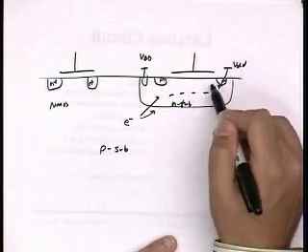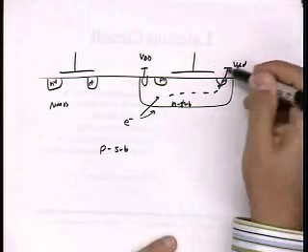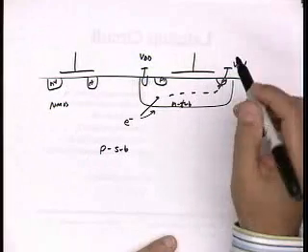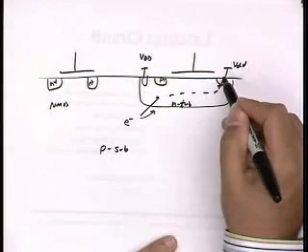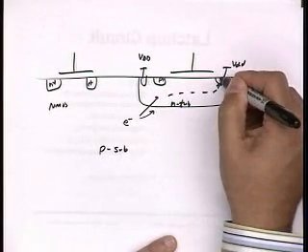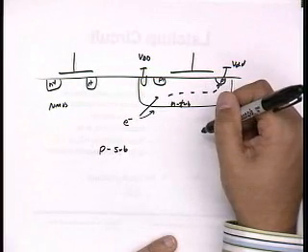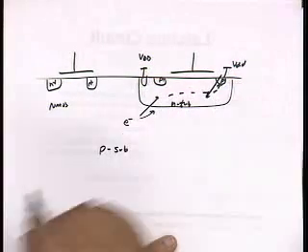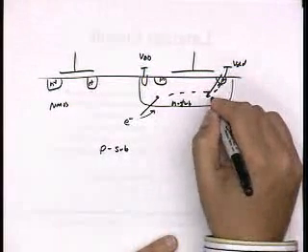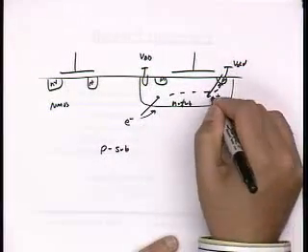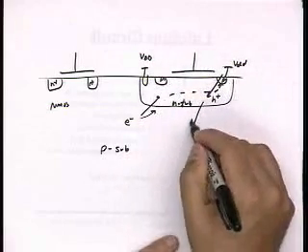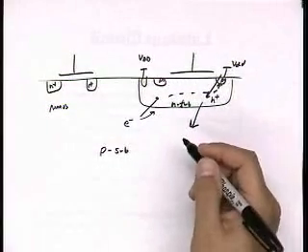Now remember, even though this junction is reverse biased, that doesn't mean no carriers cross, right? It's just a statistical thing. It's just very unlikely for carriers to cross. So the act of this electron crossing and lowering the potential just ever so slightly increases the chance of a hole also coming across and taking the opportunity, right? So a hole gets injected into this well, right? And as this hole, let's call that H plus, comes into this well, it could also recombine, or if it's lucky, it will get swept across and go into the substrate, right?